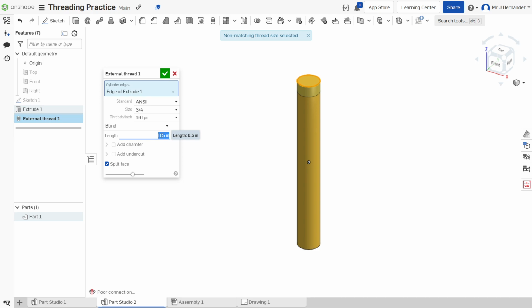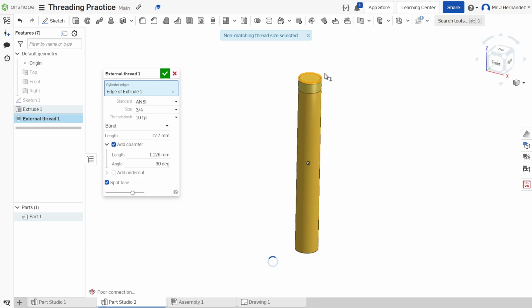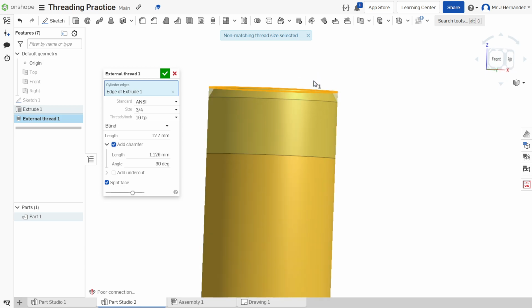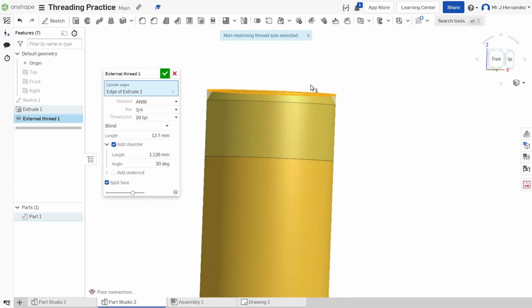I'm going to just achieve it here at 1/2 inch. And now this matches a lot the same. Now there's one more thing we can do. We can add a chamfer on here that is at the very tip and at the angle that we want. And when it does, it adds that for you already. And so you have your chamfer, and that'll fit better in the hole that has the 118 degree.